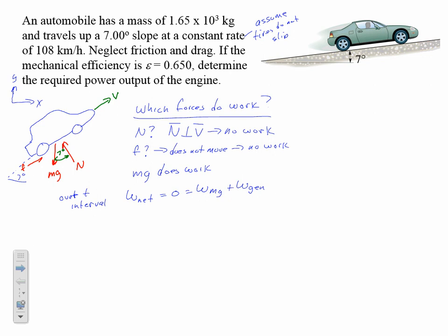So in the cylinder of this engine, assuming it's an internal combustion engine, the fuel is ignited and produces gaseous combustion products. Those gases push against the piston that then moves, and so that force on the piston that's moving is going to have a non-zero work associated with it, and so that's the work that the car is doing. That's where that work comes from.